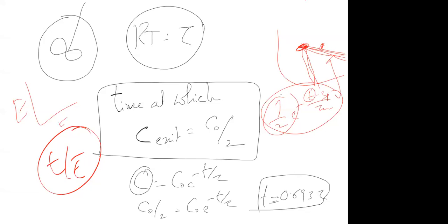Then you find T bar and plot the curve once again, E versus T by T bar, that is called normalized. If you divide the x coordinate by T bar, that is called normalized time, theta, and you would call it the E theta curve.